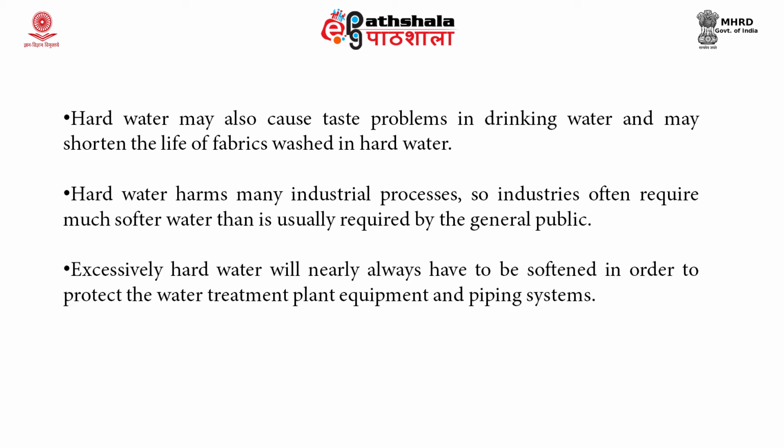Excessively hard water will nearly always have to be softened in order to protect the water treatment plant, equipment and the piping system. At a hardness level of greater than 300 mg per liter of calcium carbonate equivalent, scaling will take place. That is, white deposits can be seen on the inner walls of the pipes as calcium carbonate precipitates out of the water.